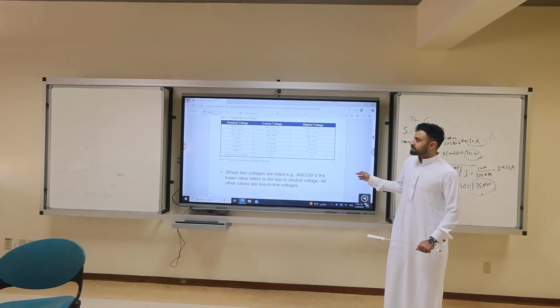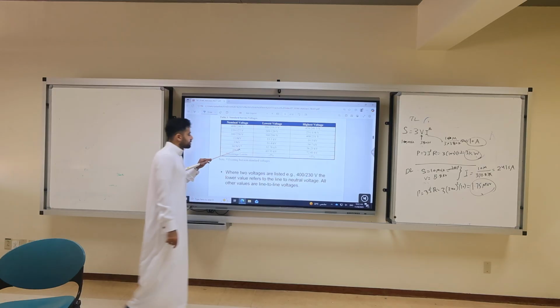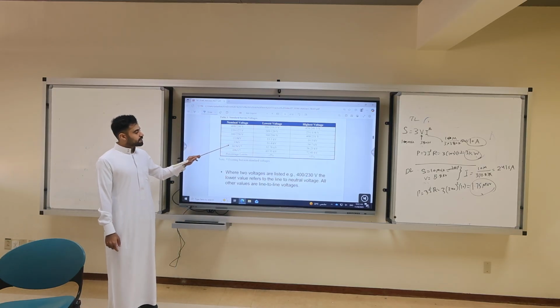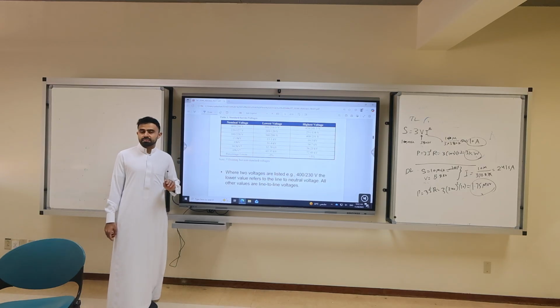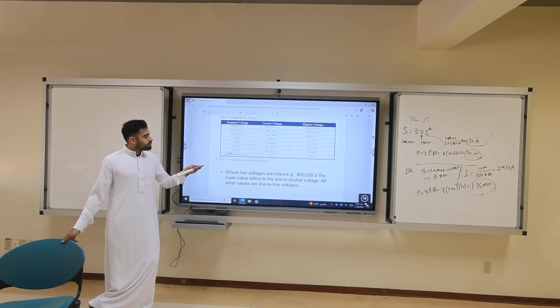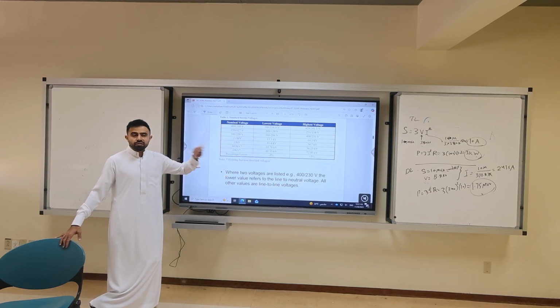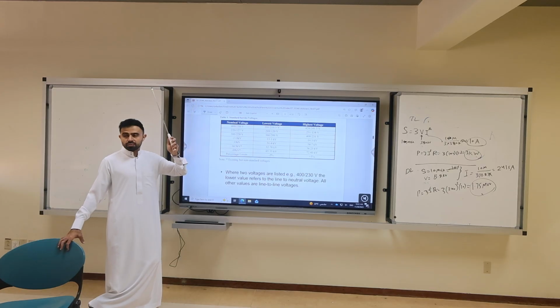For the voltage levels, let's start from the bottom. Here with the star, it's telling you 69 kV, 34.5 kV. Those are existing but non-standard. I mean, they are from the past, but after standardization, they're not standard anymore. The allowable limit is minus 5% or plus 5%. So any voltage more than 5% above or below is not allowed in operation.